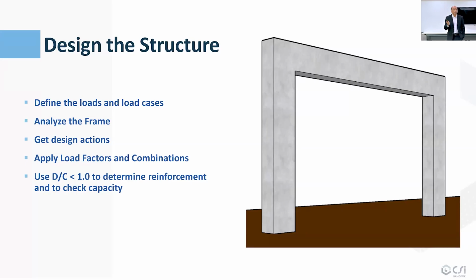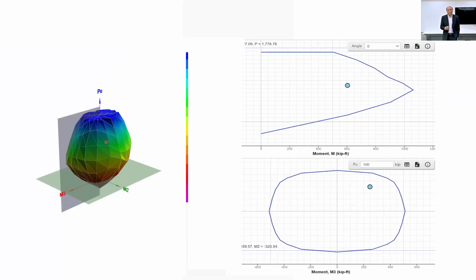And that's how the design code will work, as you know, for the capacity-based design. But the problem is that if the load applied is inside, we consider it to be safe. At that point here, we can draw a line connecting that. Let's call that length, let's say a vector, and then we can call the true capacity, or the code capacity, as C, and this as demand. Then we divide those two, we can get the demand to capacity ratio.